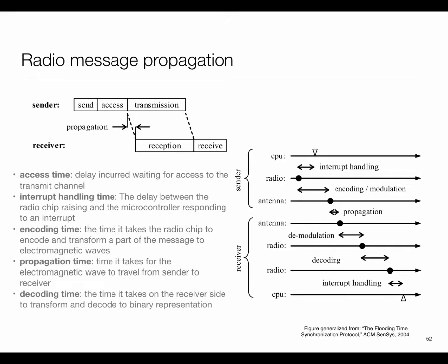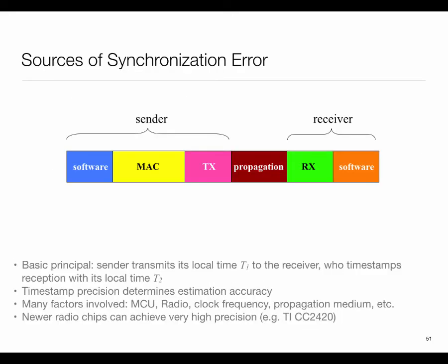The other issue that comes into play is if you are unable to timestamp well at this stage. For example, let's imagine something like the following. There are two ways I could timestamp this. My radio sent me the signal saying SFD went high, and I want to timestamp that. One way could be to tie it to an interrupt handler; the interrupt fires, and within the interrupt handler I read a clock, read a counter, and say, hey, that's the timestamp. What problem do you see with that?